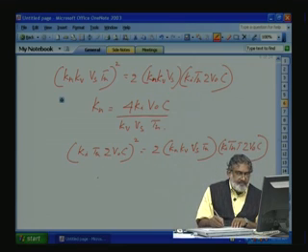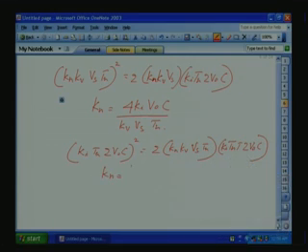From this one, so from this equation also we can find out Kn is equal to Ki V0 C divided by Kv Vs into Tn. So, from this equation we can find out Kn, substituting here we can find out Tn. So, this way we can find out the closed loop transfer function for the voltage control also.